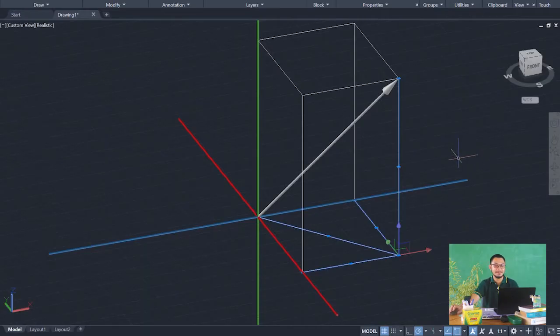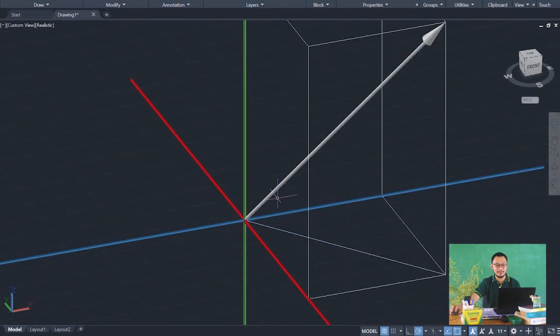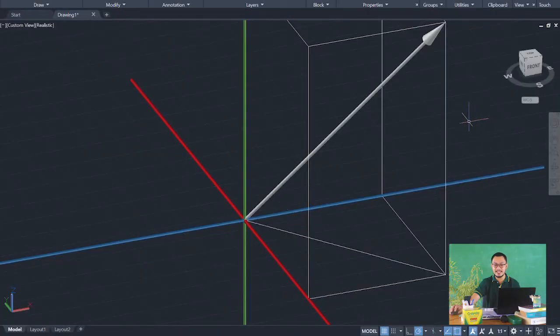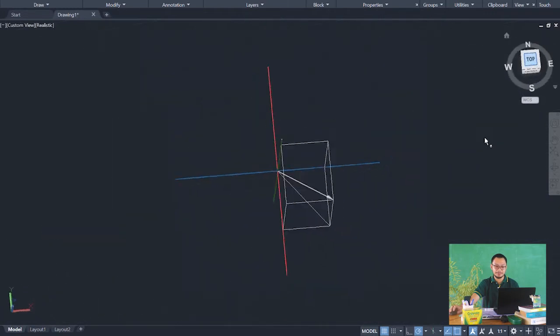Okay? So, what do we do? For example, I give an angle here of 45 degrees. Then how can you get FZ? It's very easy, we use our sine because this is opposite over hypotenuse. Right? And to get this F prime, using the same triangle, all you have to do is use your cosine. So, adjacent over hypotenuse.